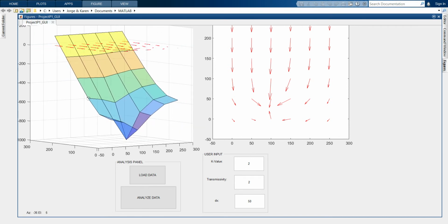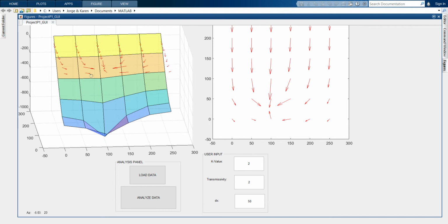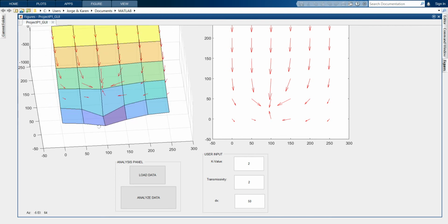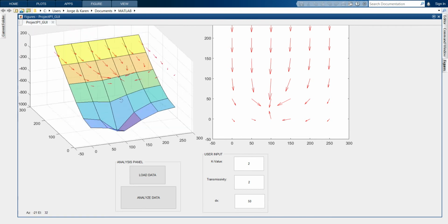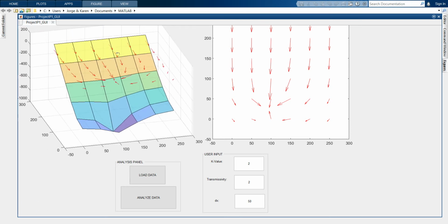Because this file was designed with the number 2 value, which tells us that there's a well in the system, we see where the well is at, and we see that because it's a negative, our Q over T value, which utilizes the flow rate over transmissivity value, is at this coordinate, and that tells us that that's where water flow will all be centralized.